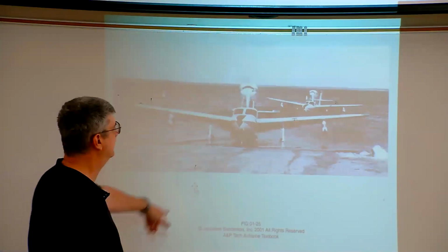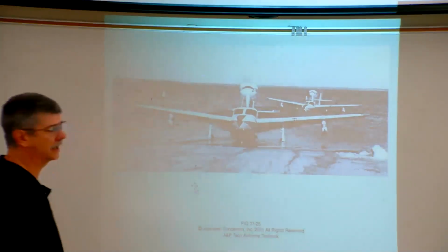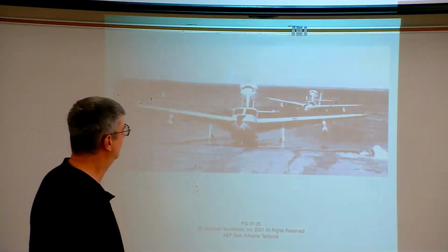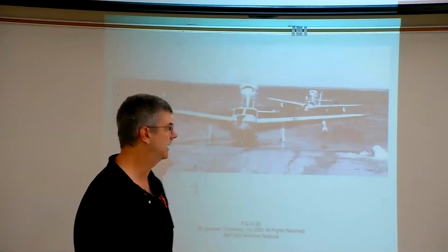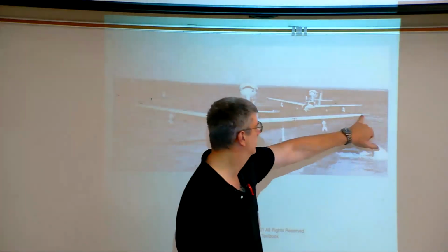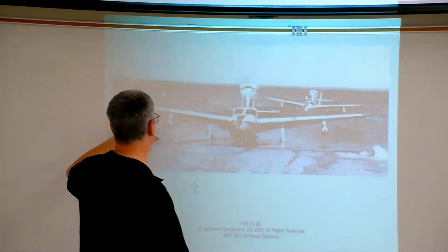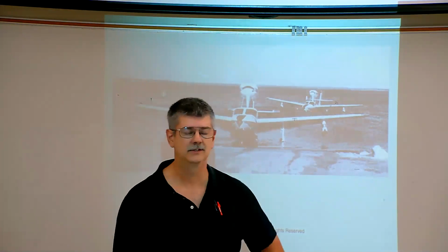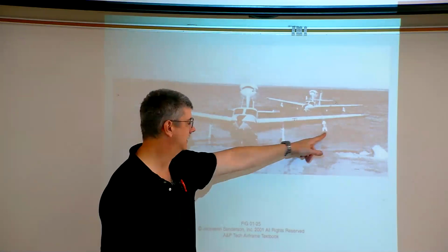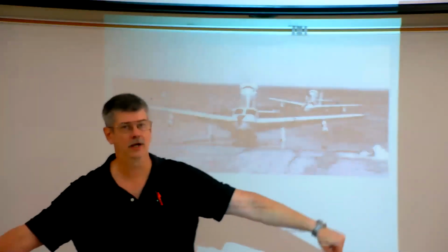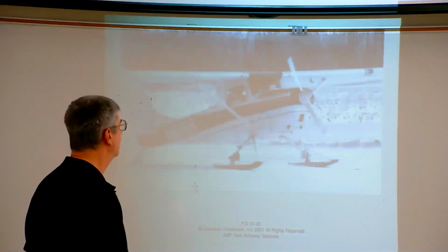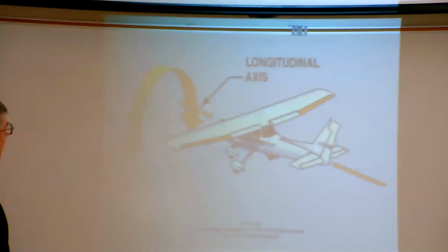This is the Lake aircraft that, when we were talking about the symmetry check, this aircraft in its maintenance manual actually had a symmetry check, which was like, okay, go from the nose or from this point here, go out to the left wing, go from this point, go out to the right wing. And the reason why this aircraft actually had one in their manual is because it lands in water, and the pontoons hitting that water can put a lot of strain on the fuselage, and with the skis and such.